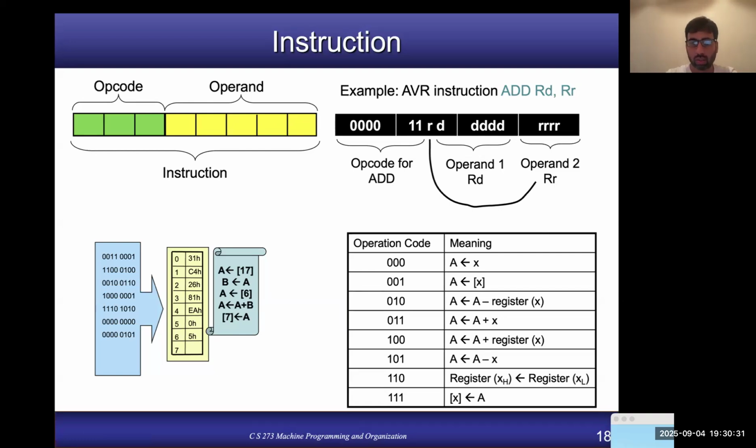So last time we were talking about different components of the microcontroller and how they are connected with each other, and then we also had a simple simulation or animation to see how a program is executed on a computer. The basic takeaway is that the program counter is responsible for pointing to the next instruction that will be executed, and then that instruction is fetched from the code memory, brought into the processor where it is decoded by the instruction decoder.